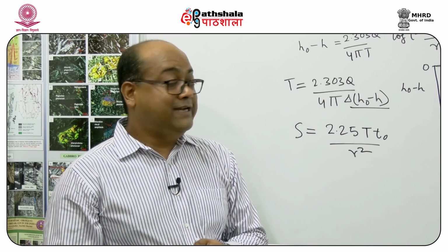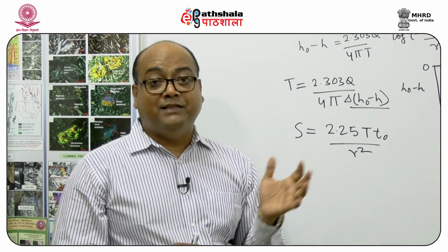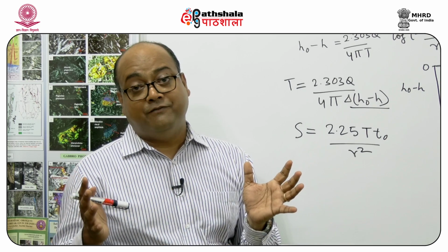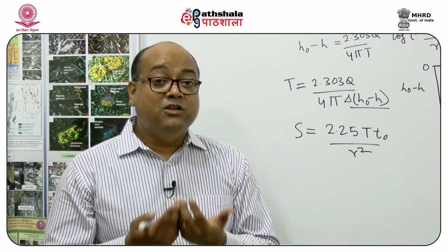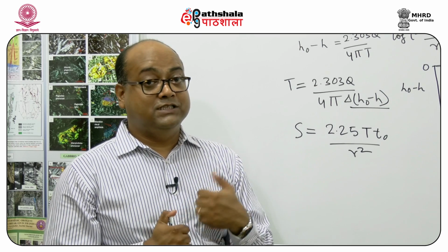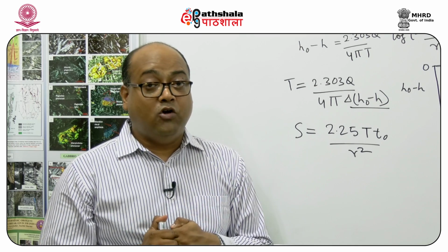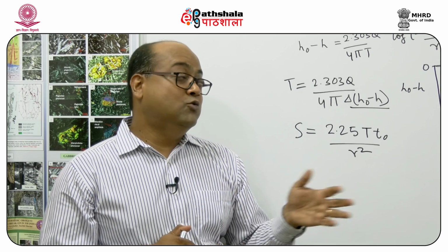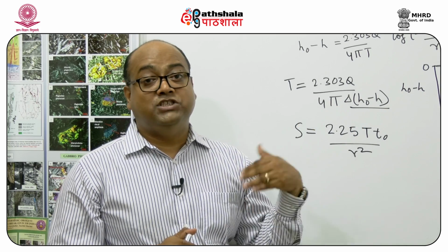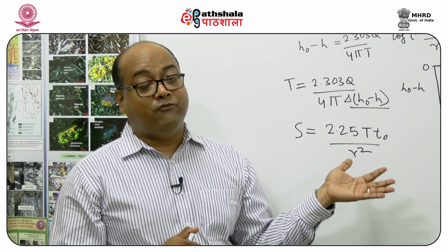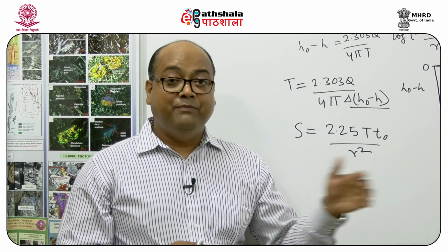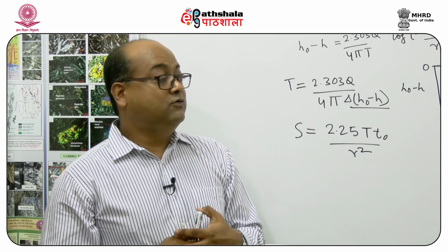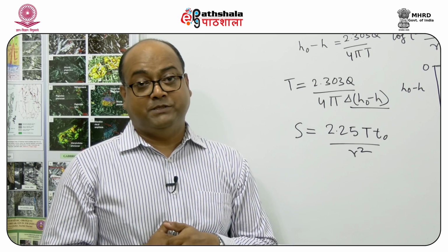And we saw two different cases. One is the Theis method, in which we need the reverse type curve, which we fit on the drawdown measurements over time. Another one is the modified method, sometimes called the Jacob-Theis method, in which we modify the equation into a linear form, plot the drawdown versus time in a graph, and find out the values of storativity and transmissivity.